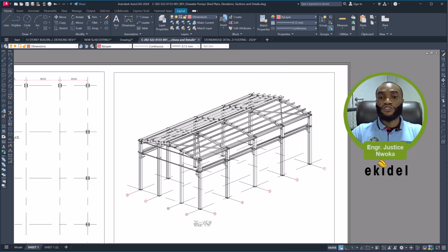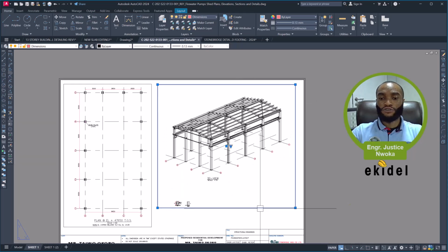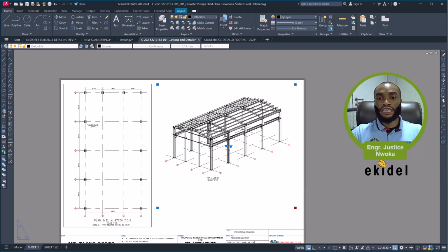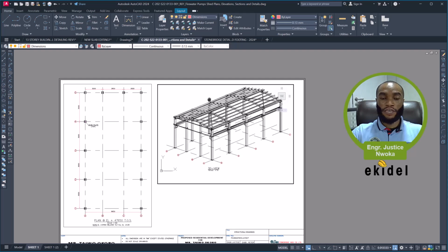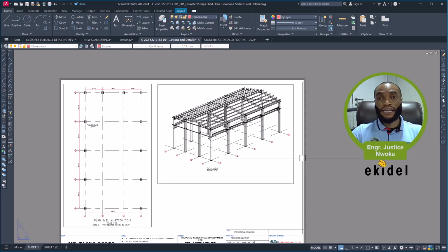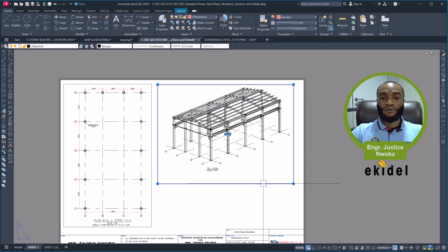So with this now, I'll come again and reduce my viewport to just contain this particular drawing, which I have done now. I'll keep this here and double click again, then pan this drawing upward a bit, because there's some space up here. I'll place this here, press PX and press the Enter key, and I'll come again, click on this place, and then do this here and do this here.